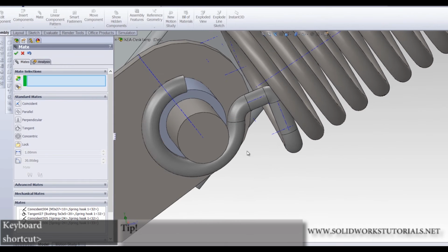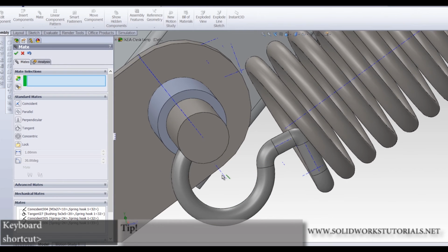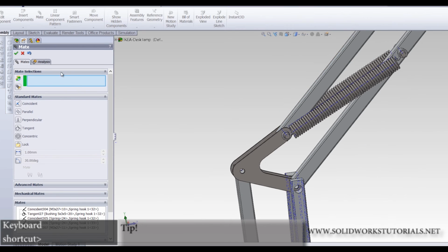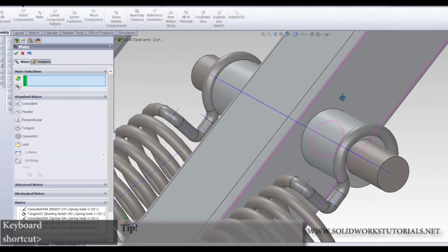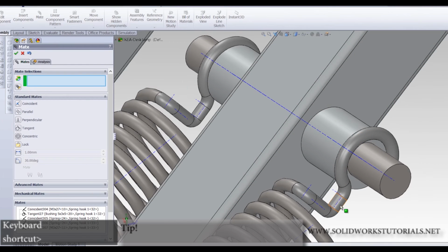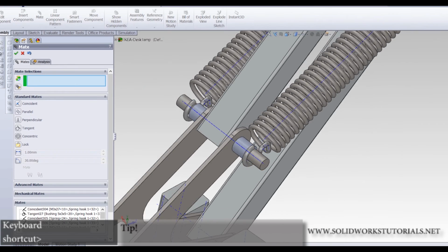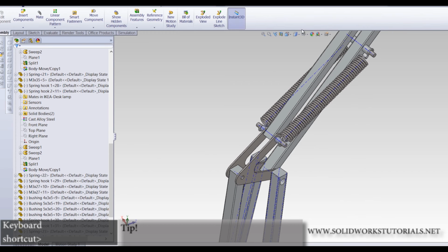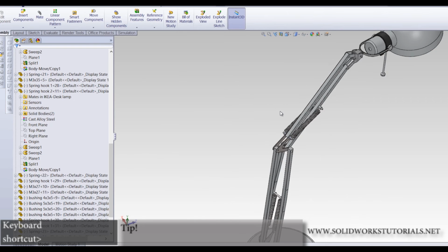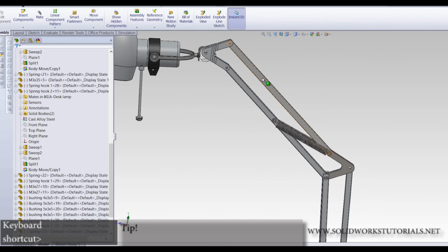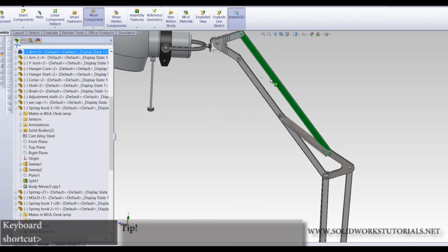Since it doesn't have a big function other than letting the arm be able to move, I'm just gonna use the same direction and not flip it, and more or less use it as an optical object rather than a functional one, because as I said, this spring is not functional. It is a static, rigid spring. It looks like a spring, but it's not. Don't forget to make these 2 surfaces also parallel. There is another video explaining the dynamic spring, the one that actually functions as a spring. You can watch that, and there everything should be normal. It's moving, so it's good.